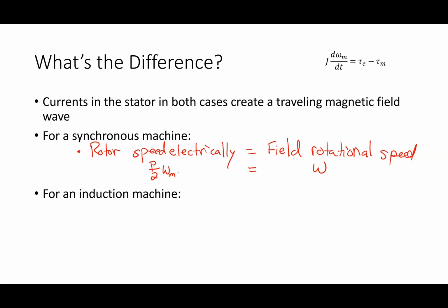Okay. So real quick, if I have a synchronous machine, how can its speed vary? It cannot. For this guy to produce a constant average torque, and that's its goal, it has to rotate at one particular speed. Now, Wednesday, we're going to go back and review that question again real quick because it relates to problem 1 on the current homework. So I'm talking about steady state stuff. In steady state, those two things need to move at the same speed.